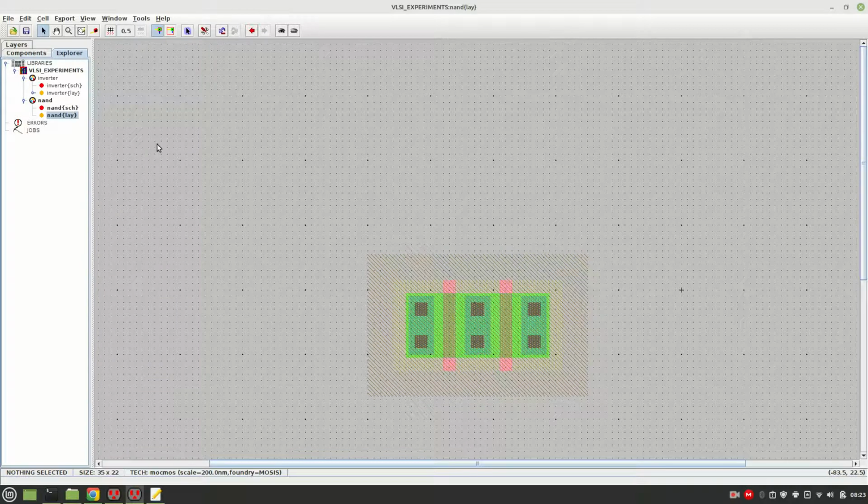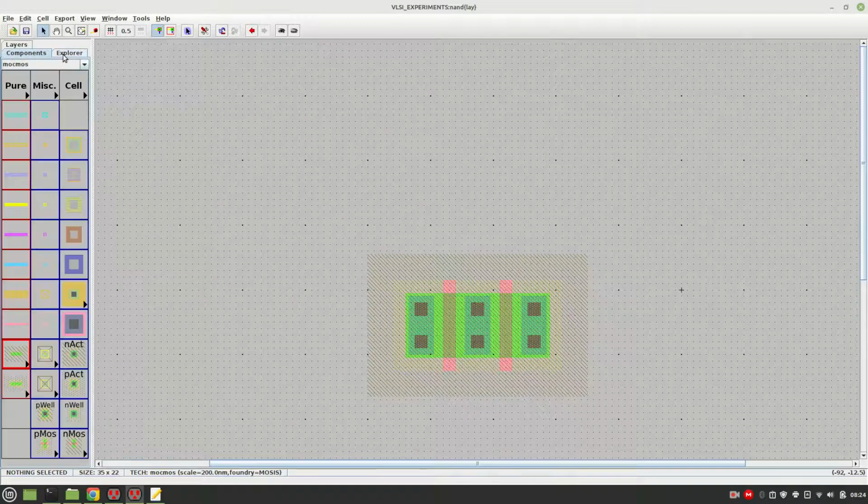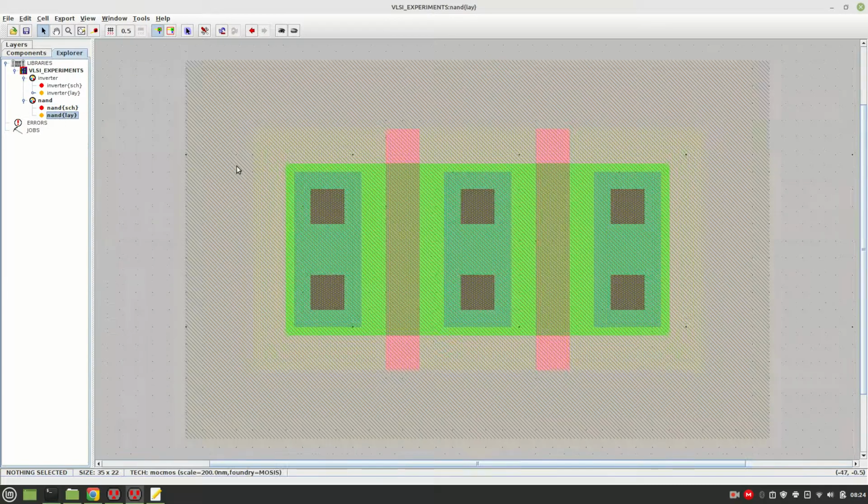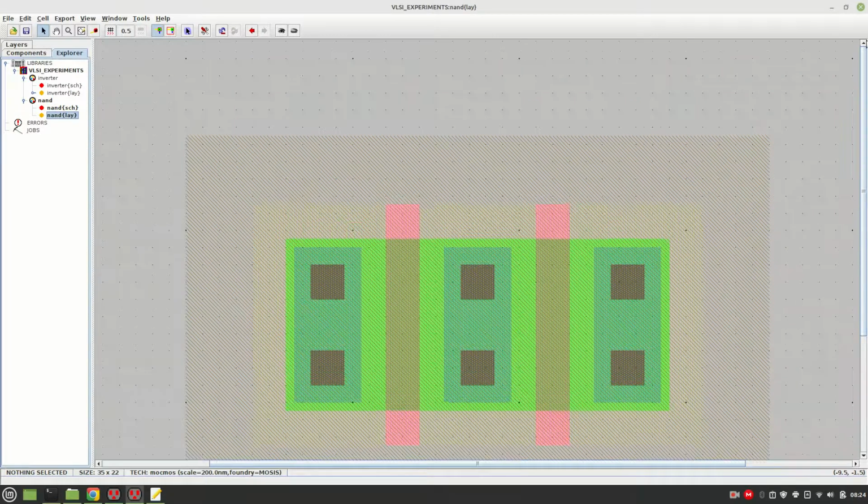Now we need to form the PMOS. For the PMOS also we can see here this source and this source have the common diffusion, so we can form the connected PMOS. Or we can even make these drain, source, gate, drain connected, so we can make a common drain diffusion or common source diffusion, anything is fine. We will similarly make the structure like this for the PMOS also.